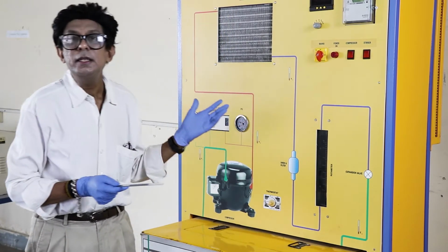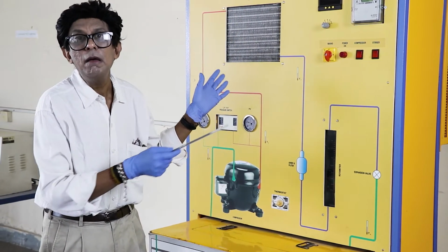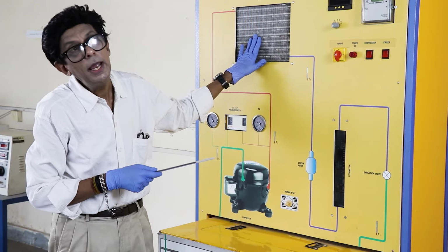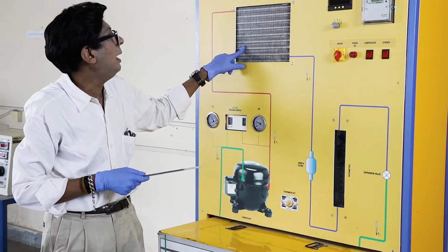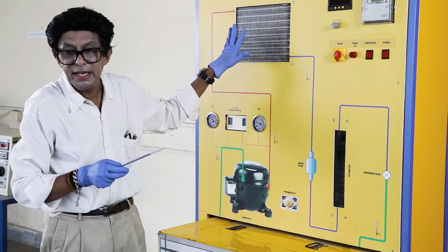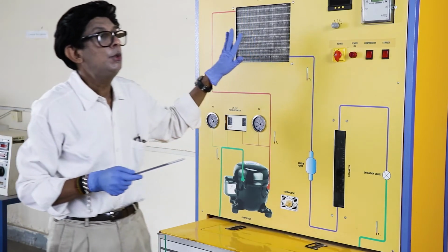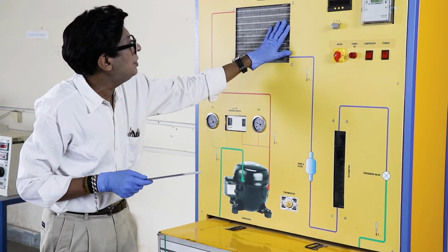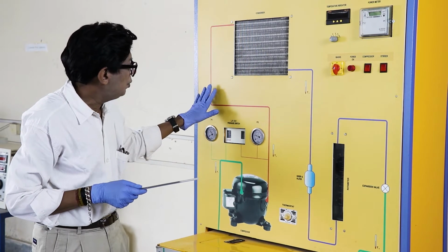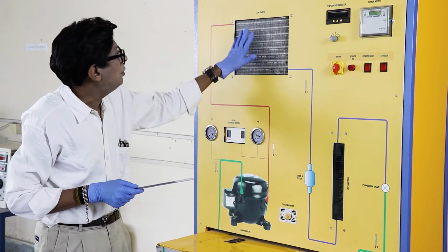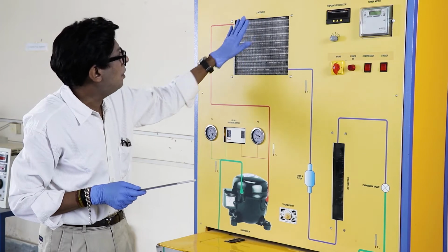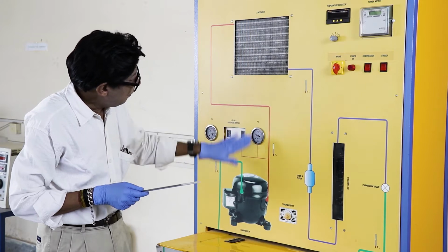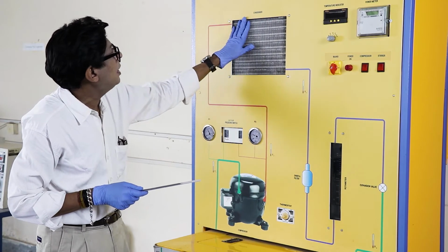And in this case here, the setup makers have directly used a radiator of the automobile. They have put the radiator of the automobile as a condenser, because a radiator is an excellent heat exchanger which is used to drop the temperature of the cooling water. Here this is a heat exchanger. The condenser is a heat exchanger which is used to cool down and drop the temperature of the refrigerant, which is coming at high pressure and temperature from the compressor, and it goes to the condenser.